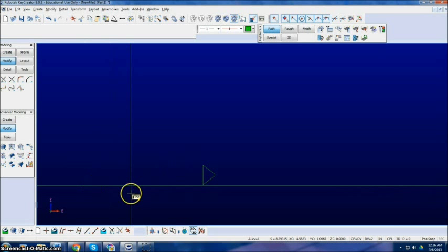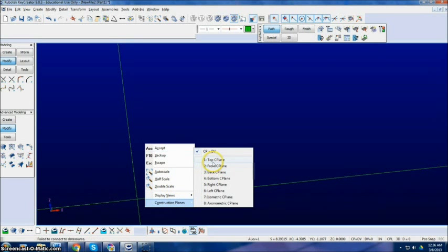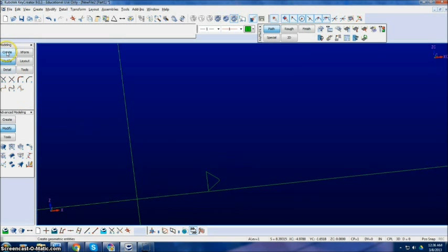The next thing I'm going to do is draw from my top view down a cylinder to add these threads to when I revolve it. So, construction plane into the top view. Create circle, diameter, my inside minor diameter was 0.8466, so that's the one to use here.